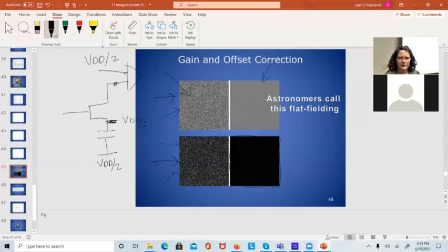So the next thing we did is we tried writing all 1s into the array, and then we did tests where we wrote all 0s into the array, and then powered it down. So you write a 1 into every cell, and you power it down, and we waited various amounts of time to see what would happen.